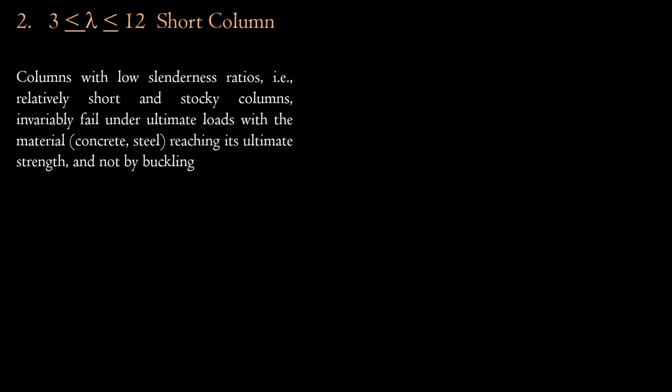You can imagine you are taking a chalk piece and a pen refill, and you are applying a force. What will happen? Definitely the refill, which has a small cross-sectional area compared to the length, will buckle, and the chalk will get compressed. The same thing is happening here. So for a short column, the column fails by compression mainly.